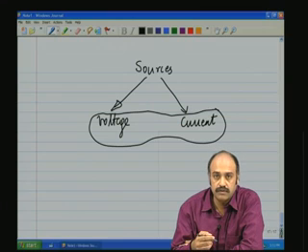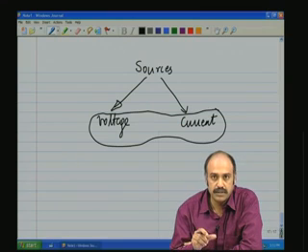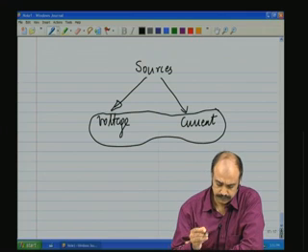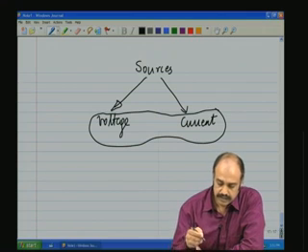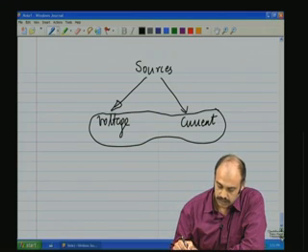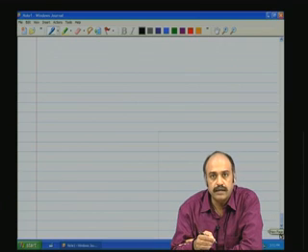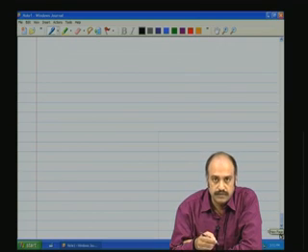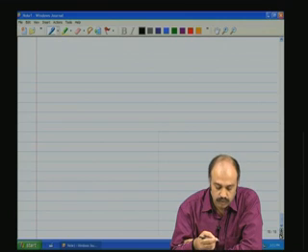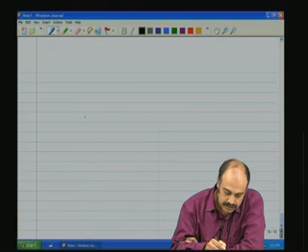This is a unique feature of the photovoltaic cell, which is special to this type of source. So how does it behave? Both like a voltage source and also like a current source. So internally, if we look at the photovoltaic cell, its equivalent circuit, it consists of a current source.